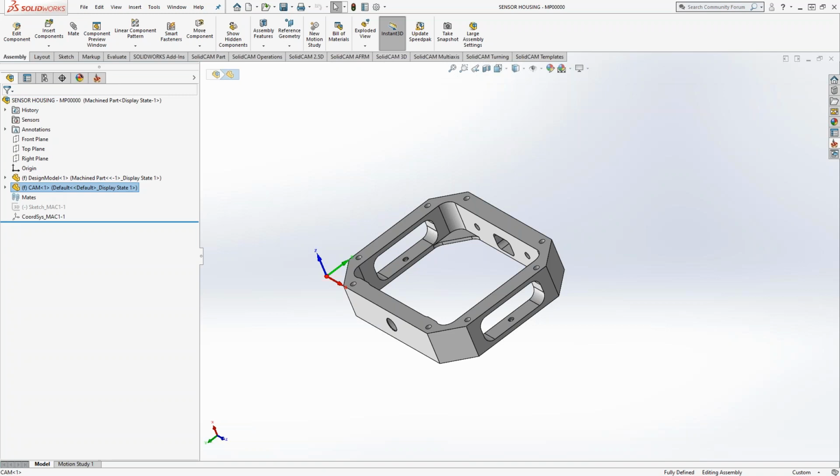Yes. Now, whichever source you get it from, you might have to do some post work on it. Post as in it's already been modeled for you, but you might have to reassemble it or set some new mates or something like that for it to be a little easier to work with. There are ways to deal with those solids when you bring them in, but that's a lot more of a SolidWorks functionality. So if you have trouble with that, as always, give us a call at the main tech line and we can help you with setting those up.